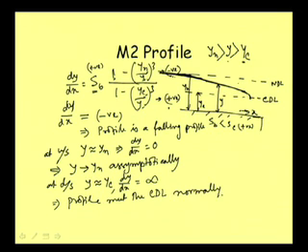Okay, perpendicularly it means. Perpendicular means this is perpendicular to the CDL line, not to the horizontal, because again CDL is parallel to the bed line. So with that respect we are saying that it is meeting perpendicularly. Okay. So that way we are getting the characteristic of the M2 profile, and there are some other finer points here.